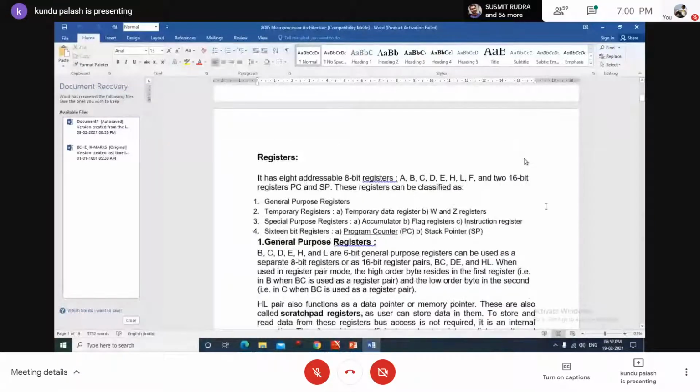So these are described here in the following manner. The 8085 has 8 addressable 8-bit registers called A, B, C, D, E, H, L, F, and two 16-bit registers called program counter PC and stack pointer SP. These two things.